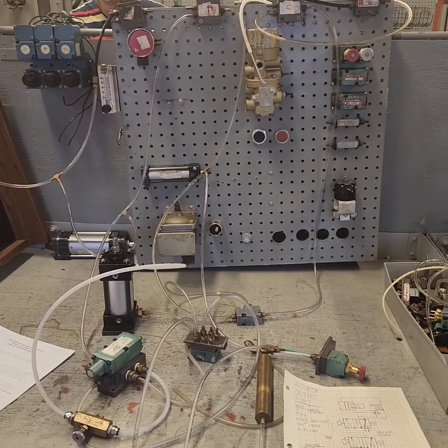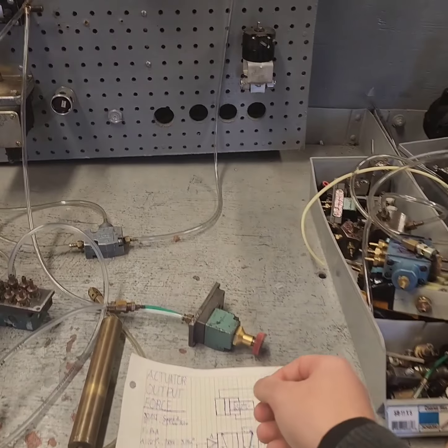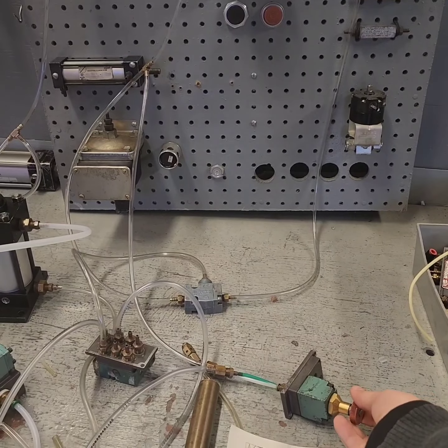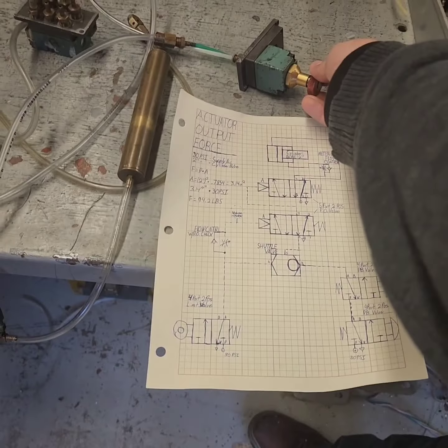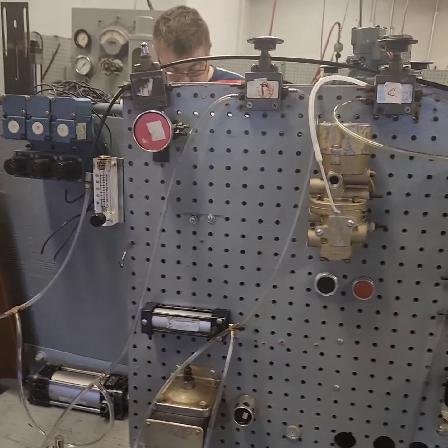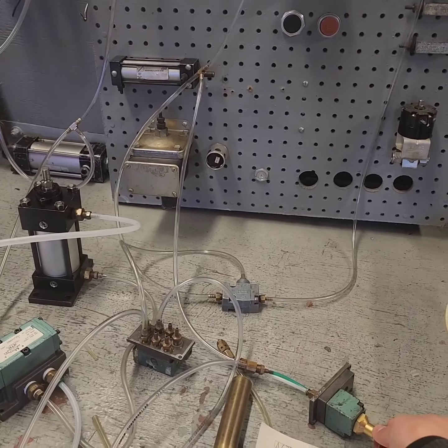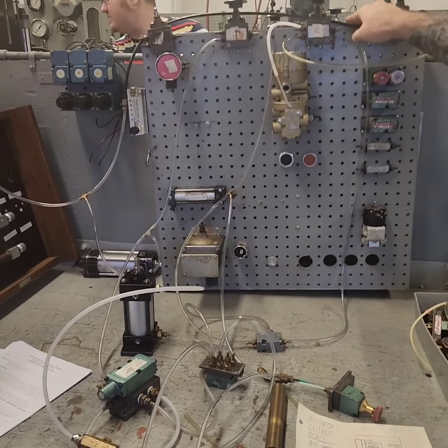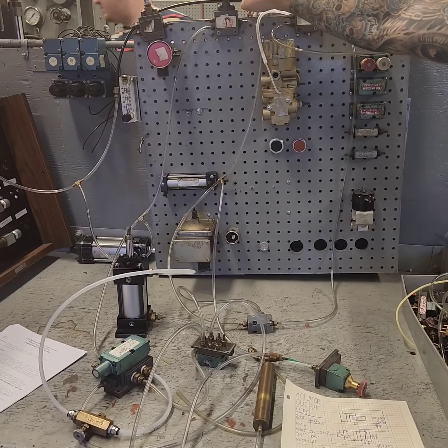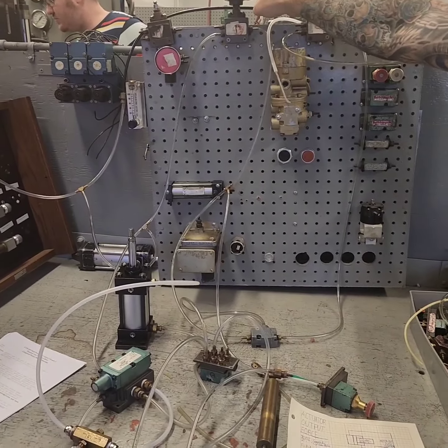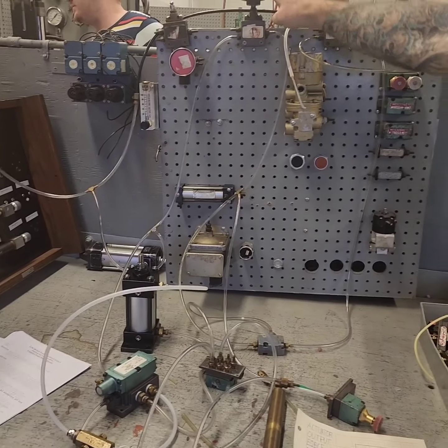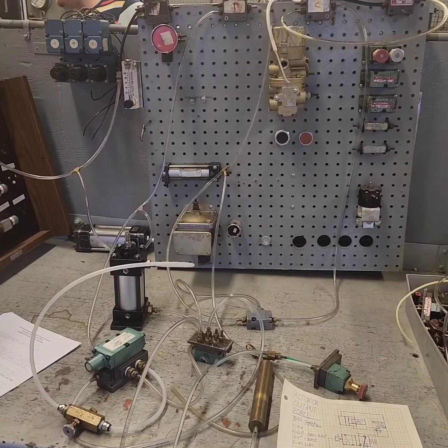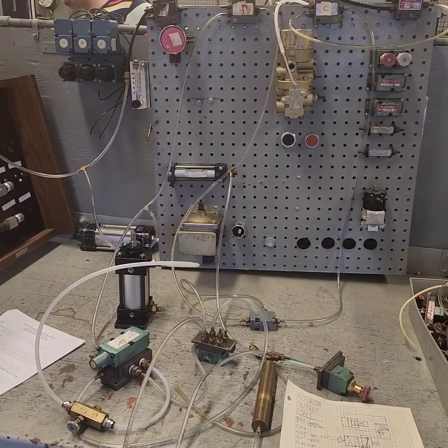And then we have our timing function as well with this flow control. Now if we close this, it's going to make the timer longer when dealing with the limit switch valve or the third push button there. So you can see that the volume chamber fills up if they press the limit switch button. Now normally that limit switch would never be hit until the circuit was pressed from the other two push buttons, and that's what actually would turn it off and cause it to pretty much reciprocate, kind of locks it in.